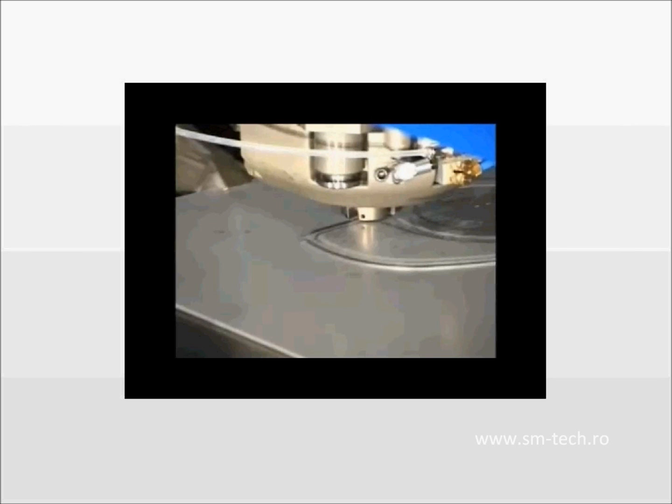There are also things you could do either before or after making that cut that can eliminate that. You can come back with a forming tool to flatten that distortion out, possibly. In a case like I show on the screen right now with this video, where I'm cutting basically a 90-degree corner, I might be able to cut past a little bit, and then start my cut slightly before, and that might help with the pinch mark. But it definitely is an issue. In some cases, it's just a fact of life that can't be eliminated.